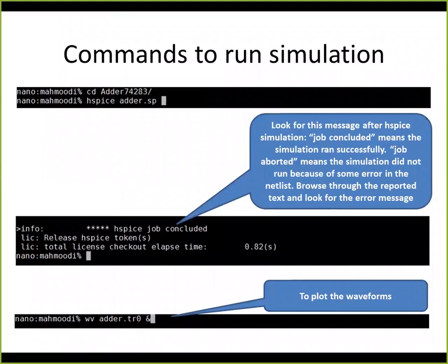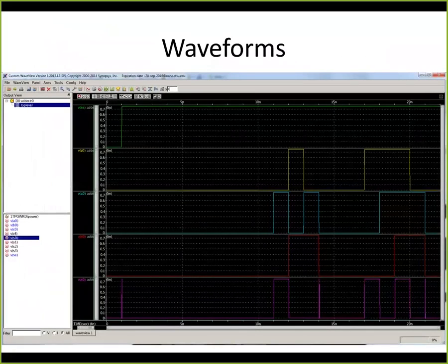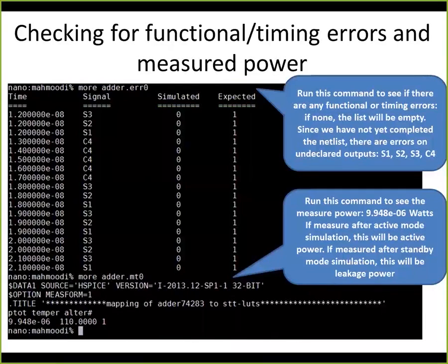And these netlists are run by HSPICE software tools on a server. And then after running, you can view the waveforms to check the functionality. We have also developed a script that can basically run this netlist automatically for finding minimum delay.